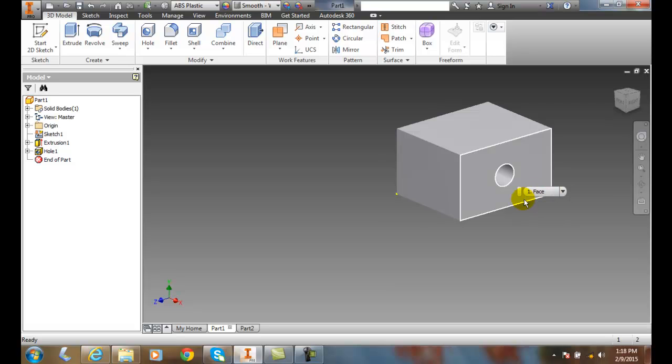Assembly constraints. When we have an assembly of a variety of parts put together, we can constrain those parts. We can mate two items together on, say, a surface. These two parts are mated or placed together. We could put an angle constraint to place two faces at a particular angle. We can place them tangent to each other. We can insert one into another. We could place something circular into another that it can fit into.